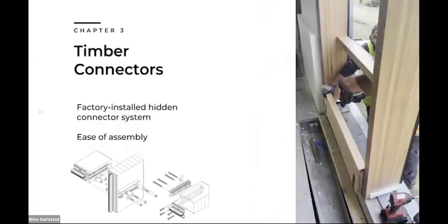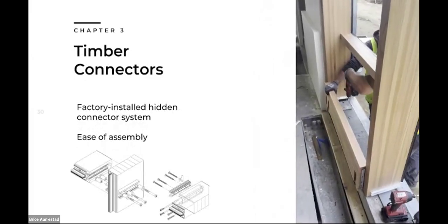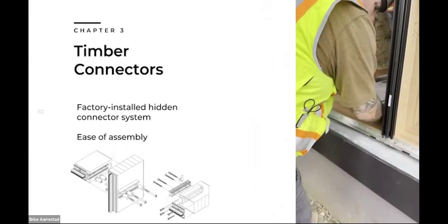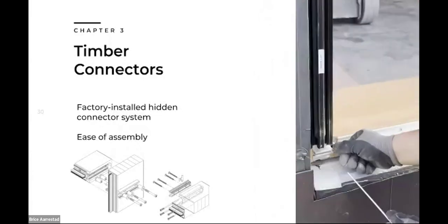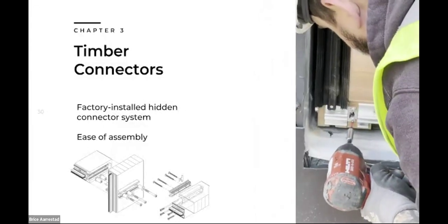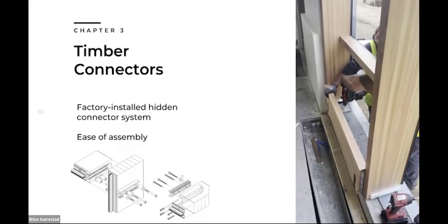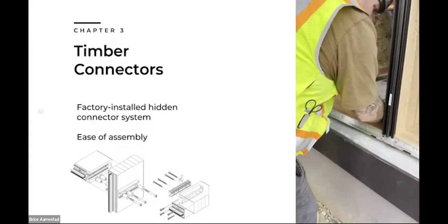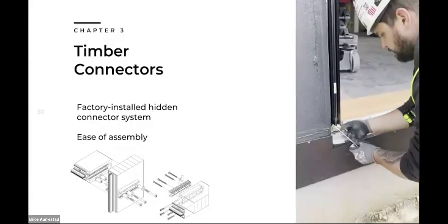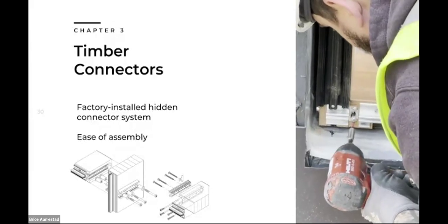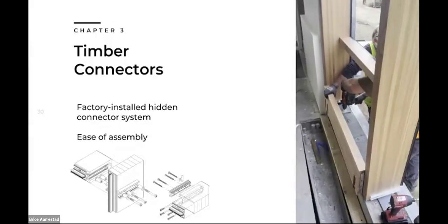The system goes together pretty seamlessly using a hidden fasteners system. So just a quick video showing how this is assembled in the field. After setting the anchors, the horizontal members are connected using these hidden fastener male and female sides, and these long nail screws lock everything together with that hardware. One thing I should note is that the vertical members are typically the ones that do all of the resistance of the wind loads. So as much as possible, those are the pieces that are continuous, that we're using for the structural resistance needed.